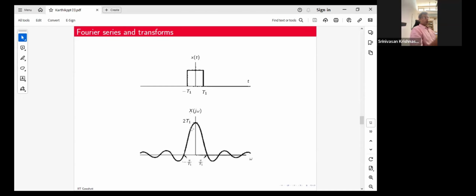So when you have an IIR filter, the frequency response would be closer in time, so your high frequency components will not be very high. The moment you convert that to an FIR filter, you will start having oscillations on your frequency response. That means you will have certain high frequency components that your system will begin to allow. That is a trade-off that you'll always need to make. You might have certain noise components that your system begins to allow, which is something you need to be careful about.